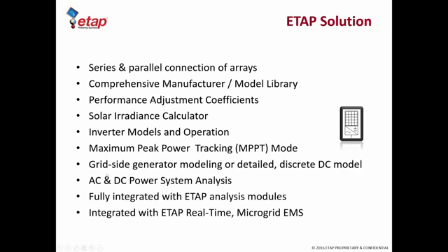You can actually have grid side generator modeling, which means that the program doesn't really want you to have too much detail on the individual bits and pieces on the string cables and so on on the DC side, but you're essentially using ETAP to model an equivalent PV farm connected to the grid, and the focus is grid analysis.